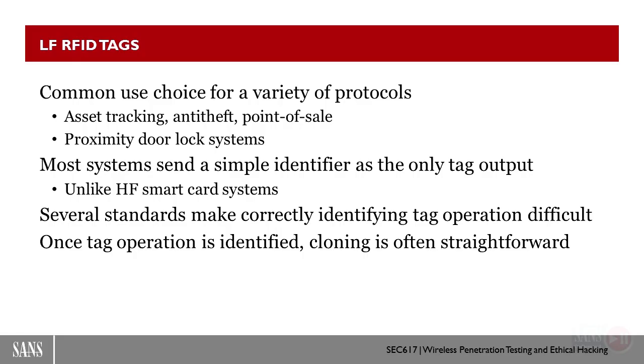Typically, on the low frequency side, we're going to present the card to the reader. The reader is going to energize the card through induction, power up its radio and spit out a very small chunk of information, typically a unique number. So it is a one-way operation. It is half duplex, so very simplified output coming from the RFID tags.